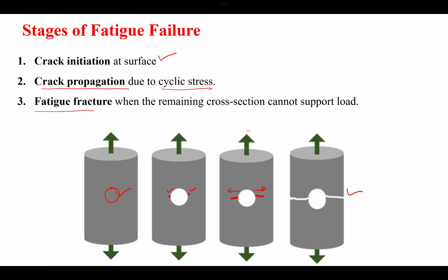So whenever our failure occurs, it does not occur instantly. It has a kind of a long time between the initiation and the failure, and that is when the crack is actually propagating. So sometimes we might not notice and we think that our equipment is working fine, but actually that crack is propagating slowly due to the cyclic loading applied on it, and eventually it will break, so everything fails.